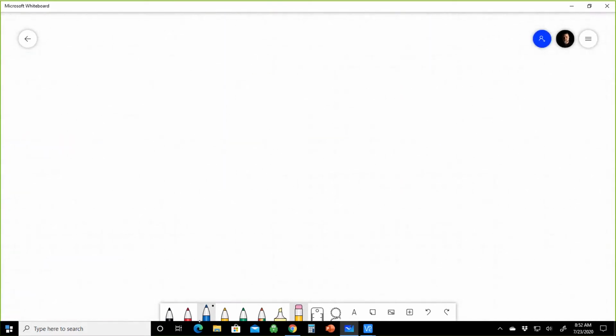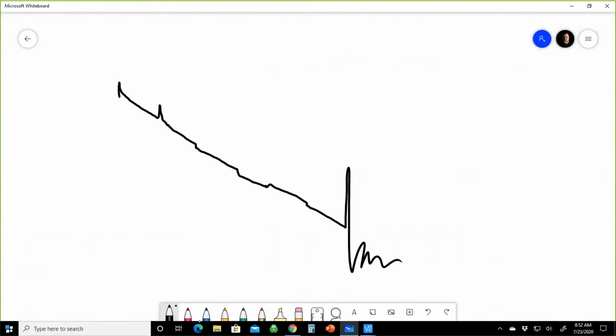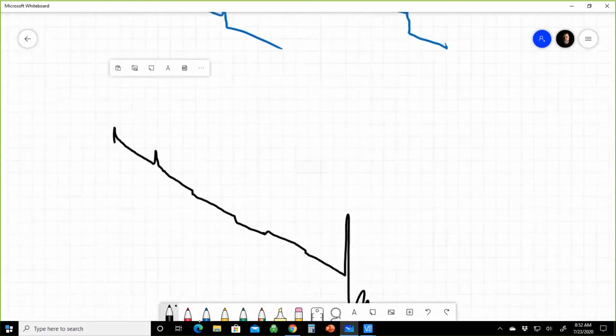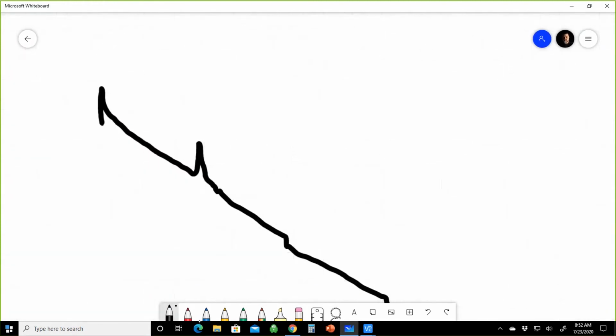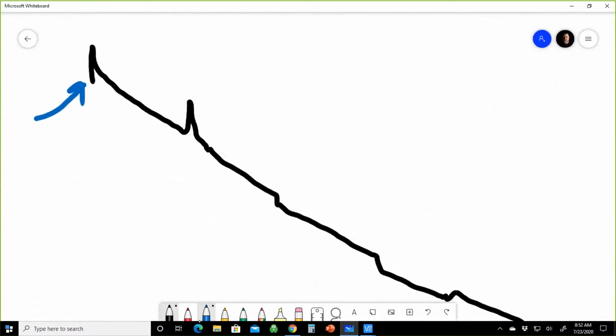So when you're looking at fibers or the OTDR trace itself, you're looking at this launch. It might look something like this. We'll say this is a high level OTDR trace, right? So when we look at this, what does this tell me? Well, we know this is the launch here. This right here is the launch because that's zero footage, right? And if I'm using a launch cable, which you should be, you should always use a launch cable, we'll talk about that. And so I have this spike here.